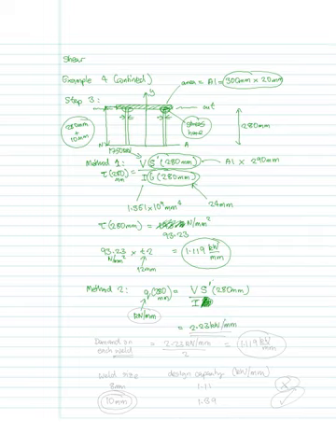So nothing has changed from the previous calculation in method 1, except that we don't have the B term. And then from there we would have said the demand on each weld is therefore equal to 2.23 kilonewtons per millimeter divided by 2, which would then turn out to be 1.119 kilonewtons per millimeter.